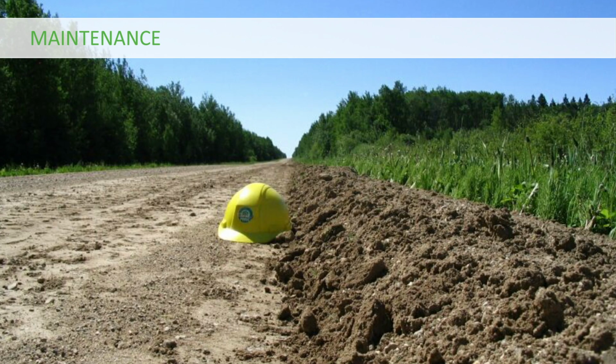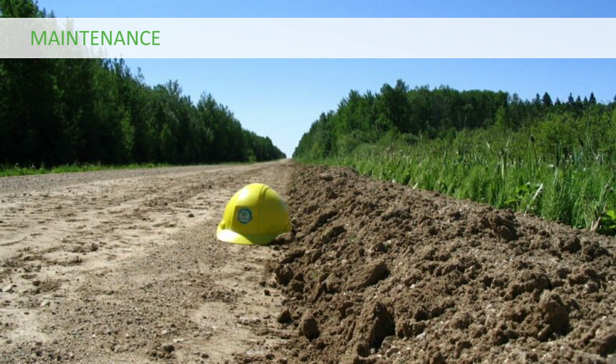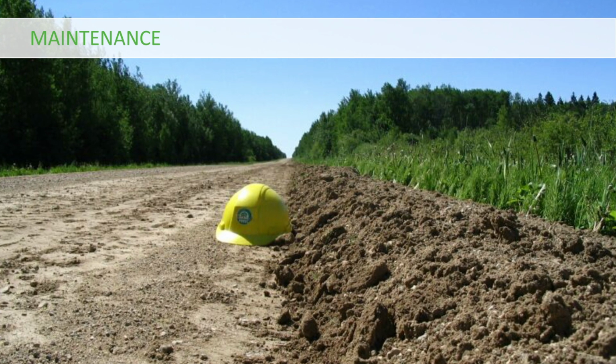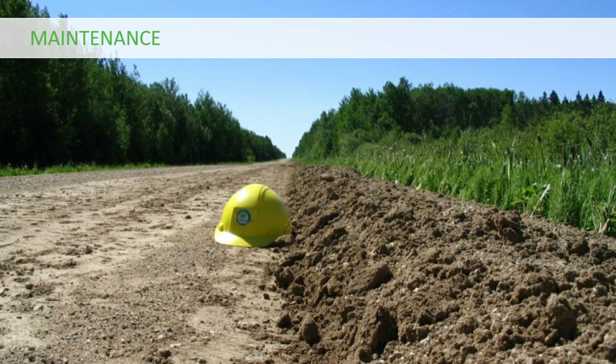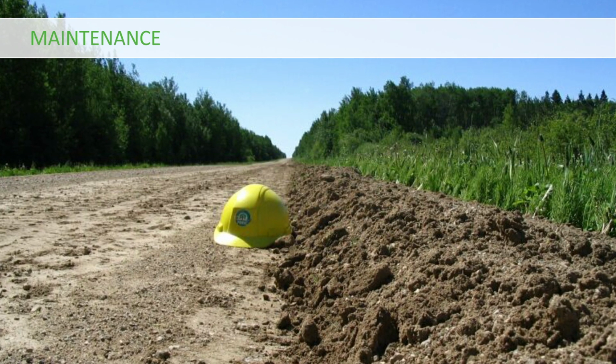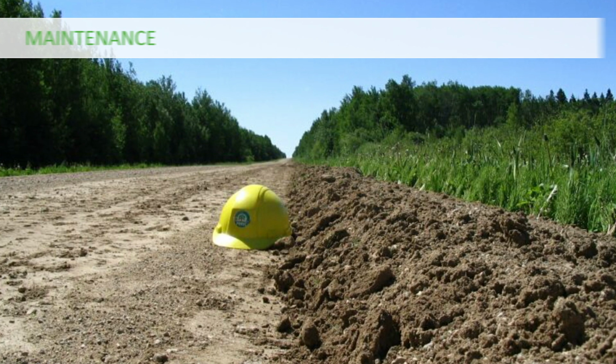Grader berms need to be breached to allow water to flow off the road and into the ditch or onto the forest floor. This can be very easily accomplished with a shovel or even a boot, but is best prevented through adequate supervision and consultation with grader operators.